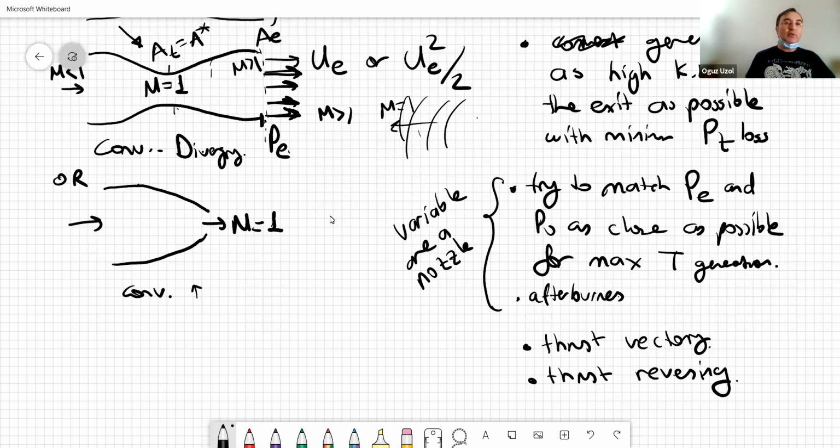But if it's a rocket engine, there is no turbine. So the exit of the combustor is directly forced into the nozzle, in a converging diverging nozzle. So gas temperatures are extremely hot in a rocket engine. Plus, in turbo engines we use, for example, hydrocarbon fuel, but in liquid fuel rockets, we use hydrogen as fuel. The heating value of hydrogen is maybe more than 2 times higher than hydrocarbon fuels. So the heat release because of that exothermic reaction of burning of hydrogen is very, very high.